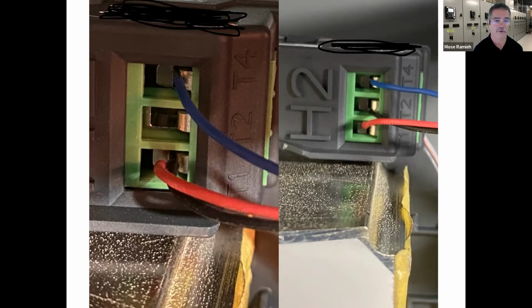So we inject current through the breaker to make sure it trips on the ground fault, and then we inject current through the breaker and through the neutral CT to make sure that it doesn't trip. So once again, prove the ground fault works, safety; prove the ground fault doesn't trip when it's not supposed to, reliability. And what we found is that the system was not working properly.